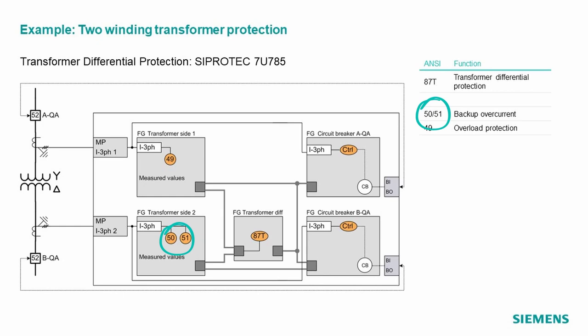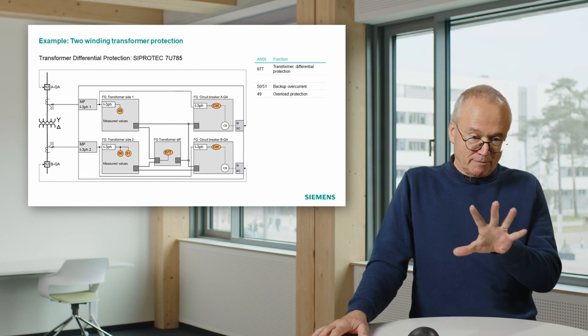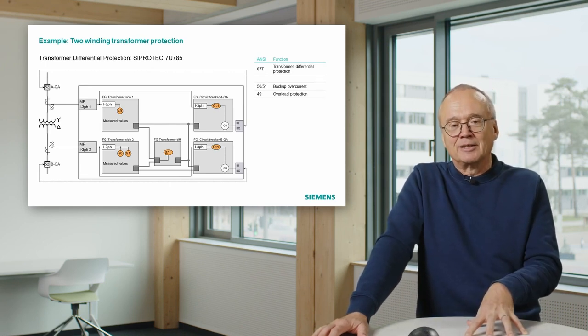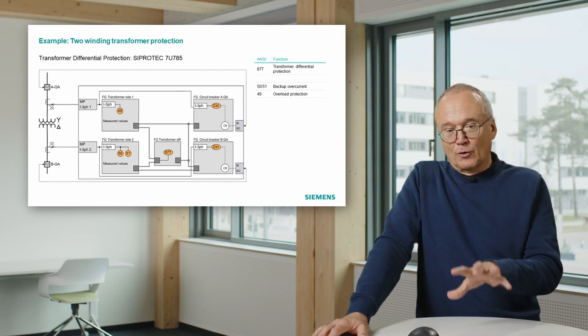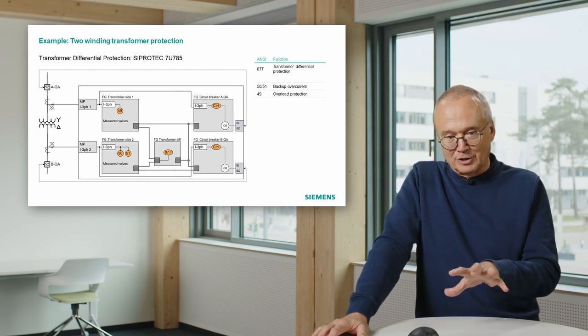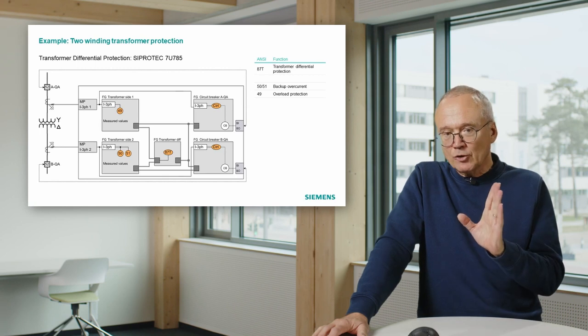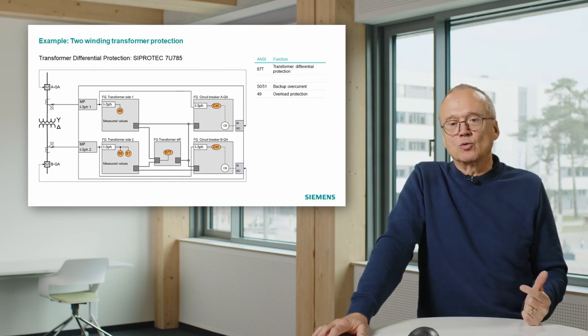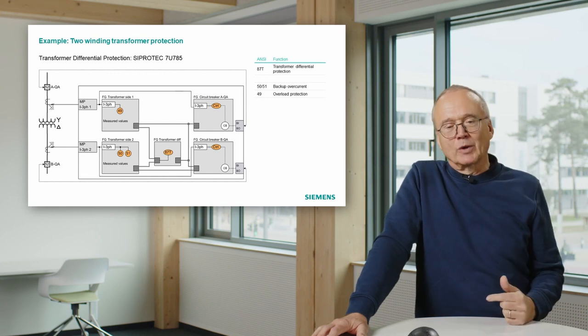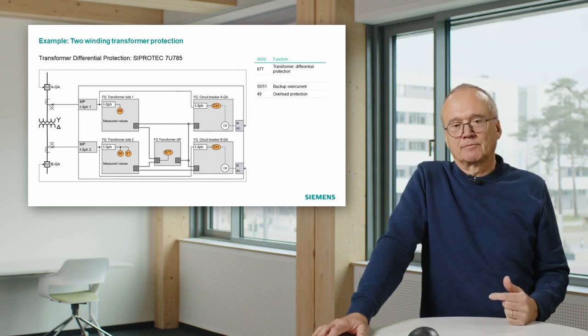And also here in this case, as the main short circuit protection is done with the 87T, the faults in the transformer are detected with 87 with a differential. The overcurrent here is mainly used as a remote backup for the following lines.